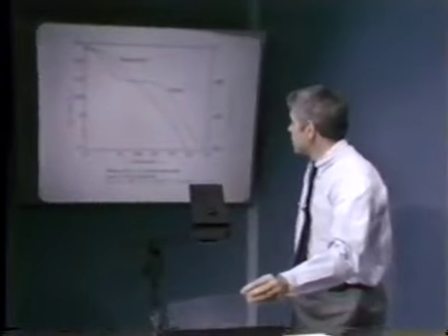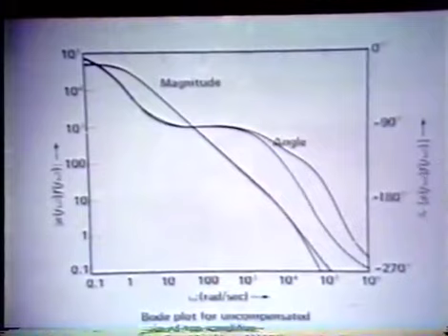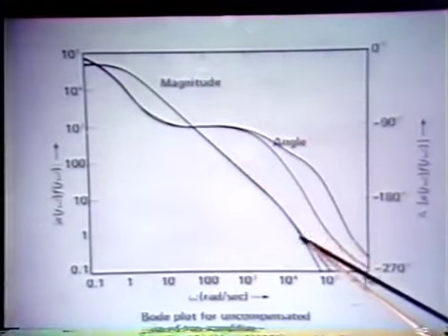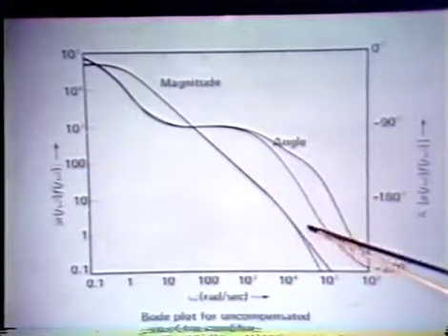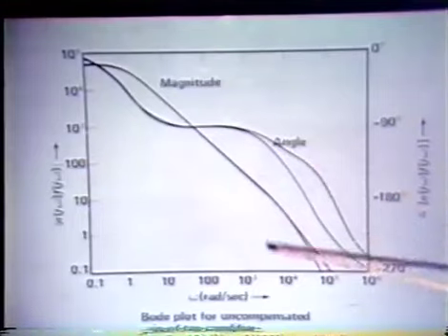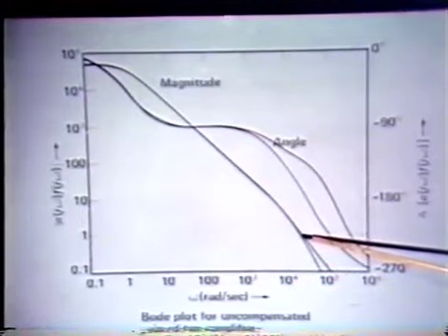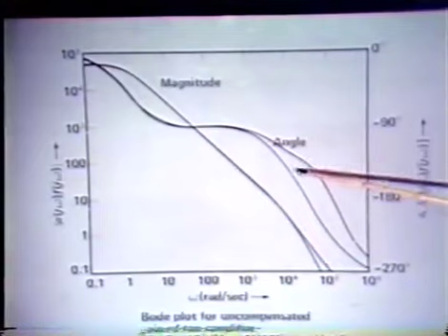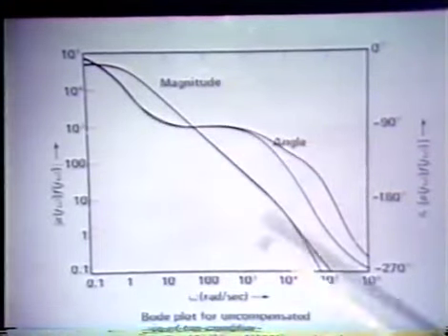Here is our original uncompensated curve, and here's the lead compensated magnitude placed on top of it. And we notice, of course, that nothing much happens at low frequencies. We begin to get significant departure from the uncompensated curve where we locate the zero, but we begin to get appreciable angular departure below that frequency. And in fact, by the frequency at which the zero is located, which is somewhere in here, we've gotten a very significant positive phase shift from our lead transfer function. We indicated last time that was what we were trying to exploit with lead compensation, and that results in a significantly improved phase margin.